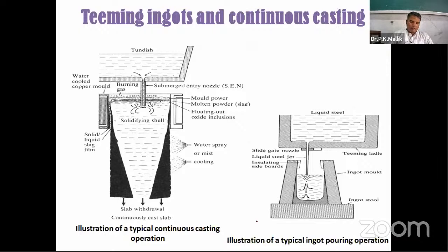So heat is lost partially by conduction through the side and bottom walls of the ladle and partly as a result of convection and radiation from the top surface. These latter losses are minimized by the use of a slag layer, 50 mm or more thick, on top of the steel, and the slag acts as an effective thermal blanket. Alternatively, a ladle cover may also be used.